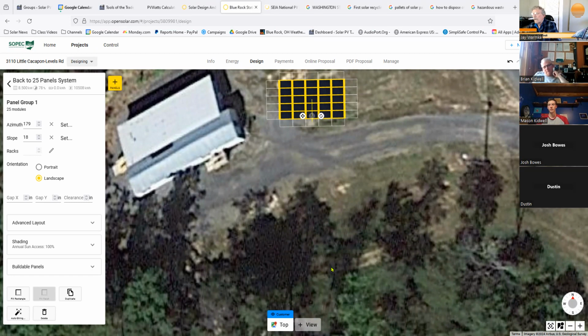But you could take a Solar Pathfinder out there and do a measurement, and that's what you would do on a site assessment for sure. Plus, remember in the wintertime, the deciduous trees are going to lose their leaves. So even in that case, it's often minimal. It still has an impact, but it's minimal.